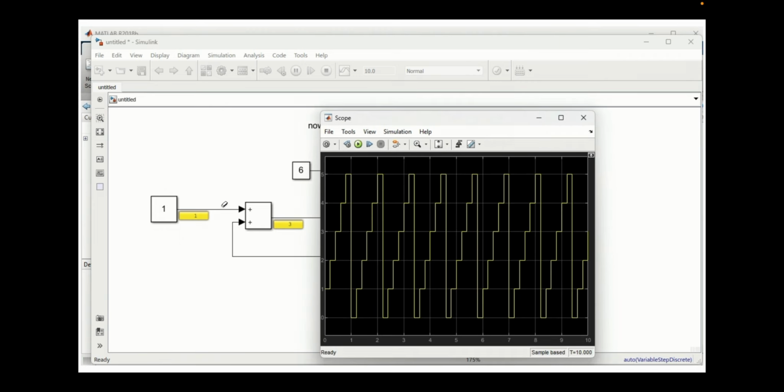So basically, in the staircase signal model, if you add the switch block with the relevant inputs, then you can generate this type of signal. This is mostly asked in interview questions, like how you can generate a staircase signal. You can also change the number till which you want to count, and again it will reset back.